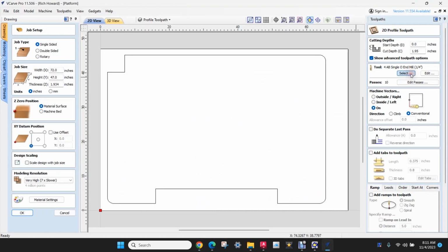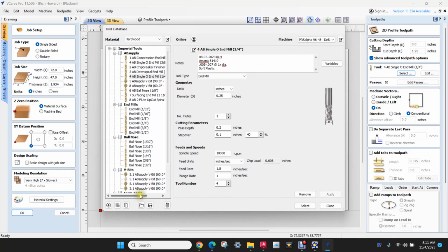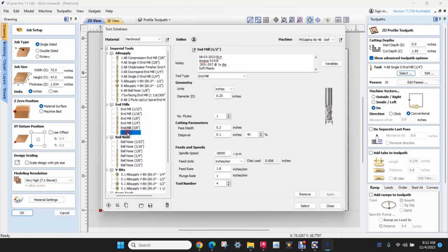Let's select a tool. Let's go with this end mill. We're going to call this tool number 9. We've got some multiple number 8s and 4s. Onsrud 60-172 MW. 0.018, 0.02 chip. Let's run, it's 2 flute. Pass depth, yeah, 1/4 inch I think would be absolutely perfect. Let's set this to 12,000. Feed rate.